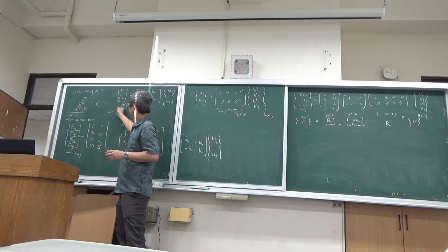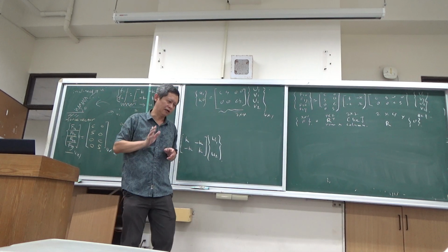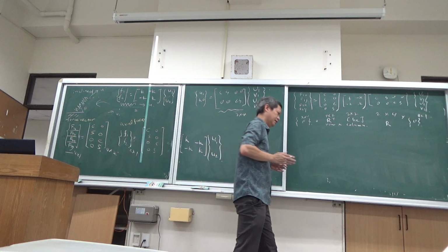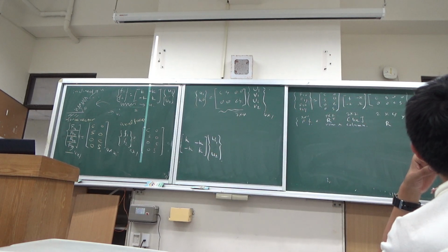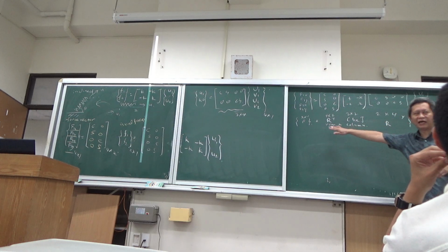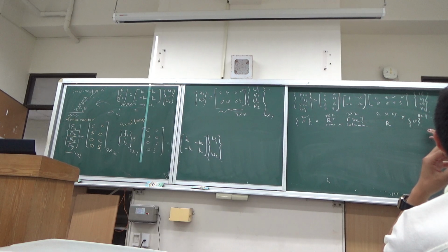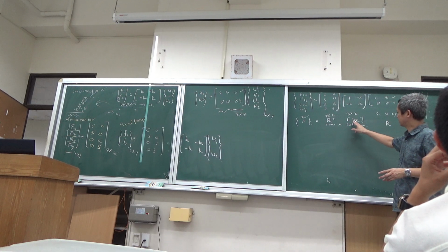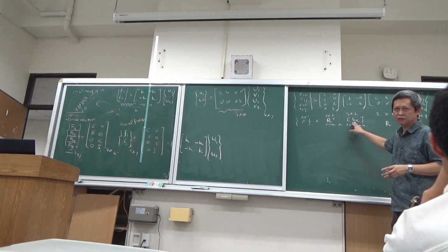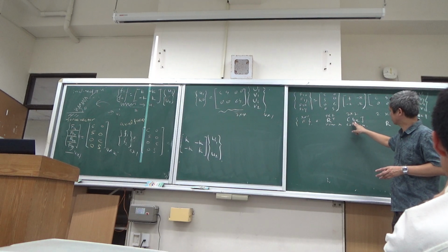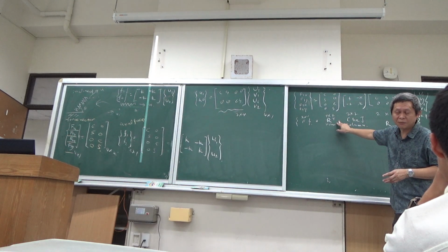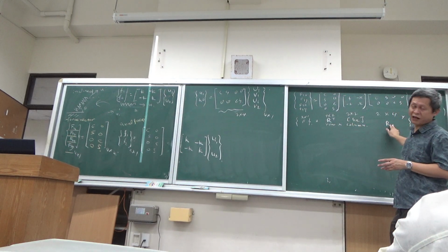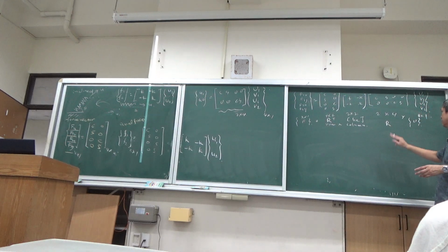But clearly, previously you only learned a spring deformation along the x direction. They are all local. But you now try to write them in the xy plane, so you have to do this rotation. So basically, the stiffness matrix you got has to be pre-multiplied by a rotational matrix transpose and multiplied with the rotational matrix.